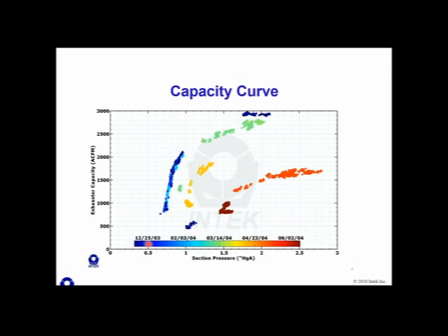Why would I put the time of year on this plot? Well, we didn't have the measurement, but that's related to the seal water temperature being delivered to the cooling water on your vacuum pumps. The seal water temperature is very important for liquid ring vacuum pumps. It acts as almost like a small condenser, and so keeping that cold is really important.